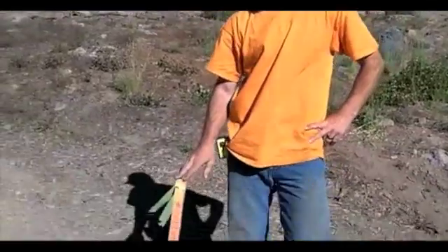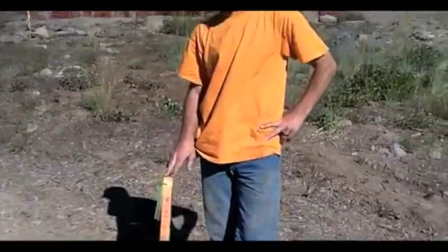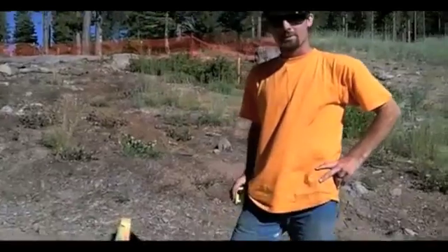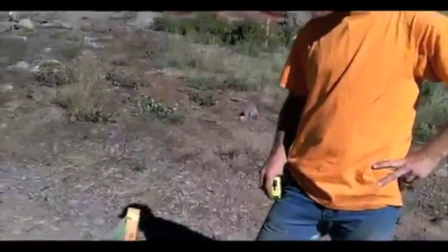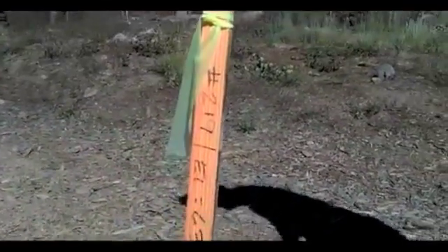Construction and excavation. We're going to talk about grading stakes. It's the first step you want to take to learning excavation. They're important because they show grades, they show cuts, they show fills, they show where everything's going to be on the job site according to the plans. The first number you're going to look at is going to be on your plans.